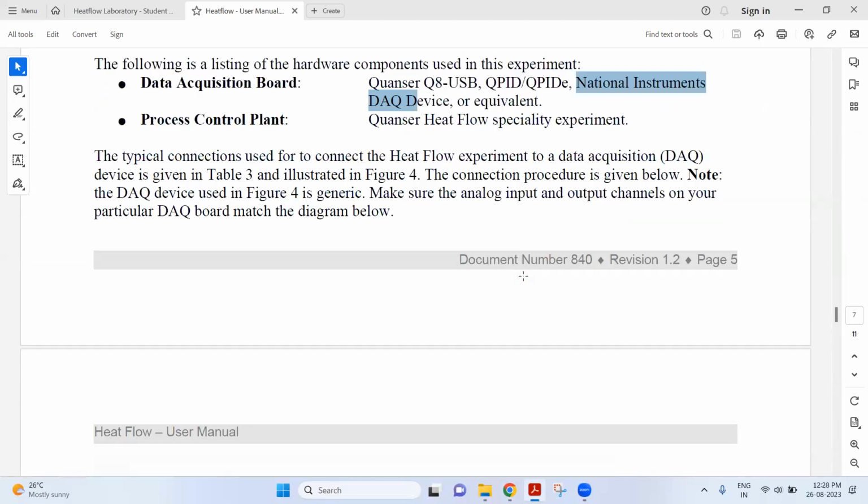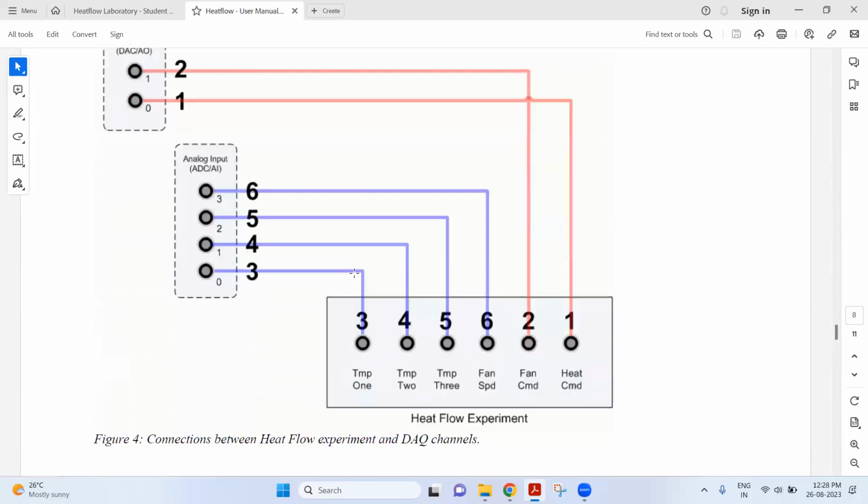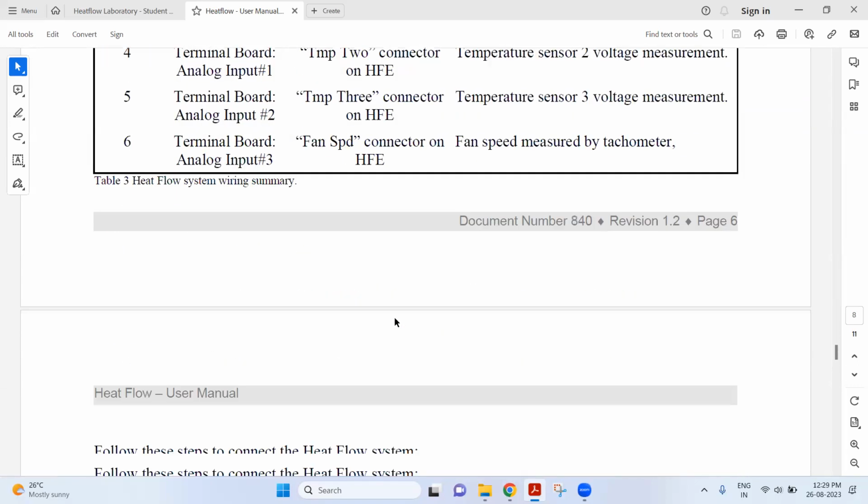Did you use LabVIEW or MATLAB? I think we have to use the physical equipment as well as MATLAB. We get some results, and then we use MATLAB to do some of the processing. LabVIEW is a software. It works with a National Instruments DAC device. When you give signals in LabVIEW, real signals will be generated from the DAC. For example, you give a 5 volt signal in the model, and actually 5 volts will be generated in the National Instruments equipment and given to the device. That is the data acquisition, DAQ.